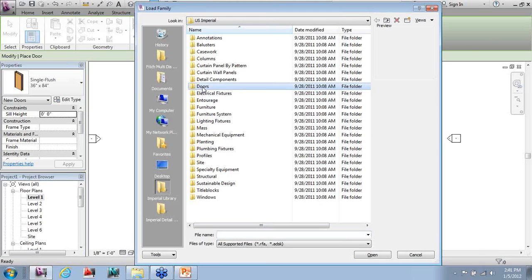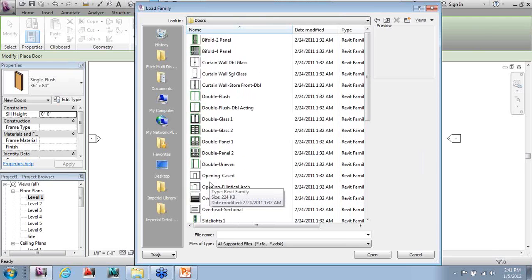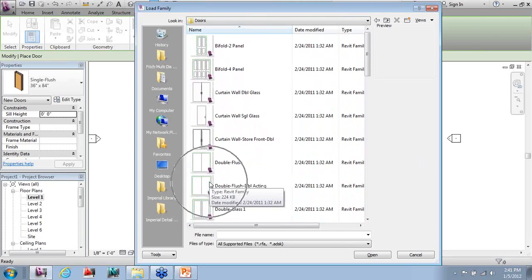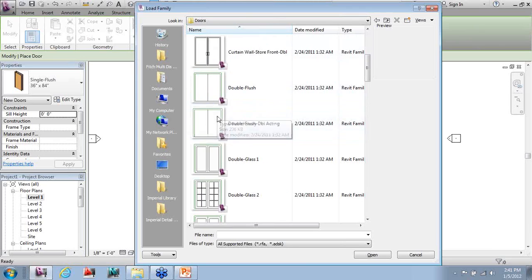As an example, if I were to select the Doors tool, I would see all the different doors that are available to me. For those of you using Windows 7, here is a great feature, and this is not an Autodesk feature, this is Windows 7 in general. If you hit the Control key and wheel forward with your mouse, it allows you to get a little icon of any of the content that's available to you. Just by holding the Control key and wheeling in slightly, I can see all the doors that are available to me.